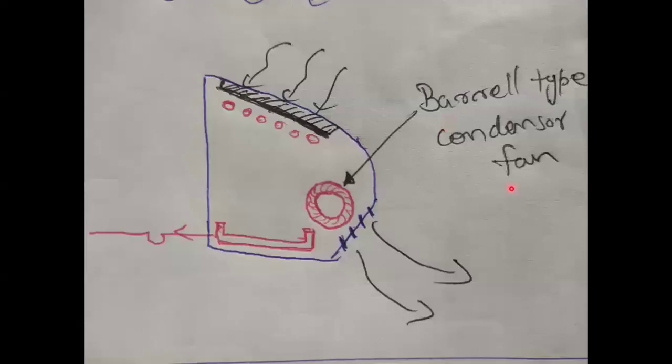You can see this now. This is a barrel type centrifugal fan. It's not the condenser, it is a centrifugal fan. And these lines you can see right here are the supply louvers. You can see the fins, the blades, which control the airflow. If you turn on the swing mode, they start to move, isn't it? So those are the supply louvers.